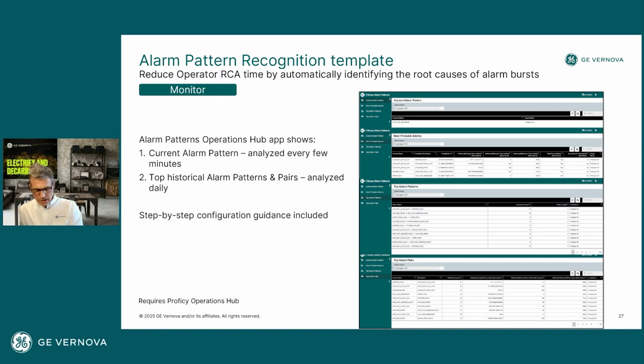Secondly, alarm pattern recognition. This is again a template that can help our SCADA customers that produce a lot of alarms to identify recurring alarm patterns and sequences, and really identify the root cause of alarm bursts and sequences online.